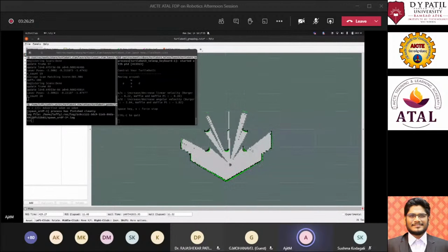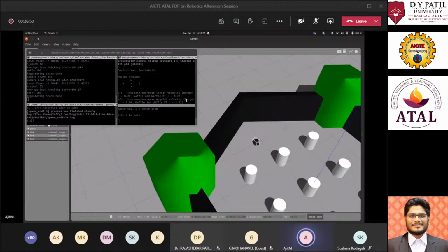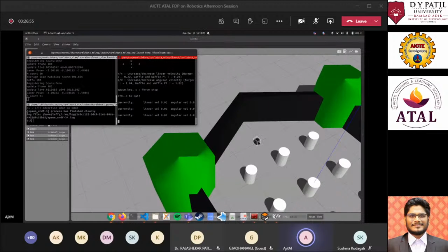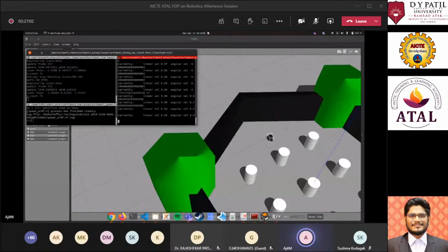This is the 2D LiDAR data, and these white boxes are where you can move the robot, and these black boxes are where you will hit, or basically the area where you cannot move the robot into. So if we just move around this specific world, it will start mapping the area. So let's just move around the map, and you can visualize the map which is coming in.